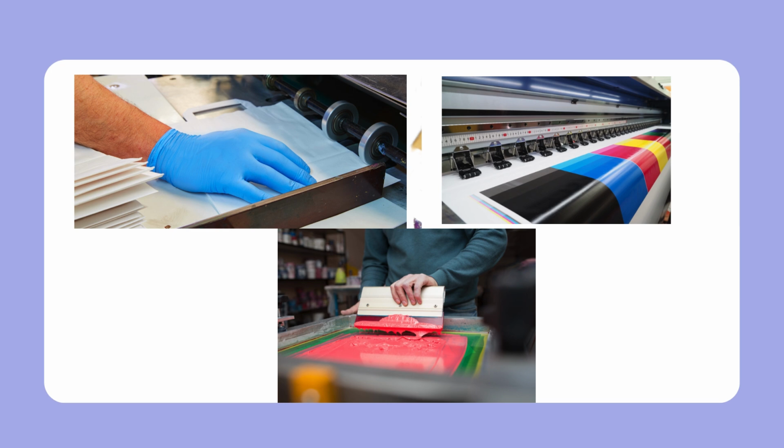Flexography and screen printing are versatile, using flexible plates and quick-drying inks for plastic and paper. It is fast and cost-efficient for large volumes, and estimators should consider direct and indirect costs as well as efficiency gains from high-speed production.